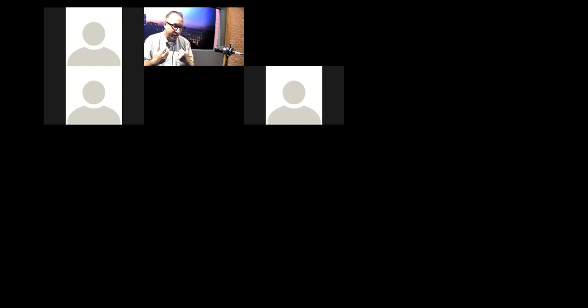And if I, as a SWPPP writer, say, this is the standard we're going to use, then if I put that in the SWPPP, then that's what they've got to do. But that doesn't mean that's the only option. These FODs are great options, and they just need to be effective. So if we think we can do it in 30 feet, great. If it takes 60 feet, fine. We just need to make sure it's effective and actually doing the job. But I really like them. I'm going to start specifying them a whole lot more for certain types of projects. Now, if a project has only one entrance and it's the only entrance they'll ever have, then the traditional way is probably just fine.